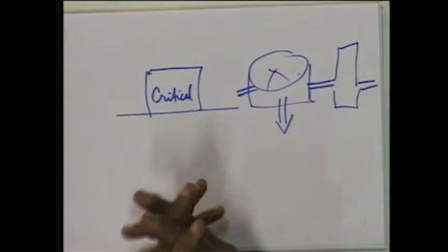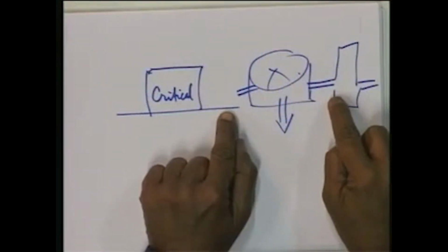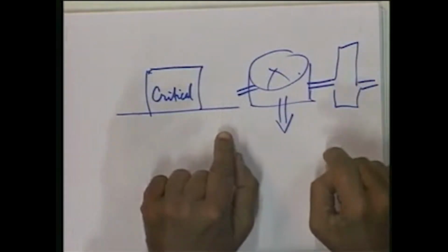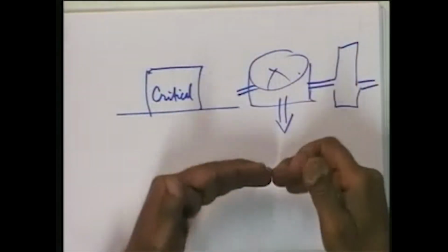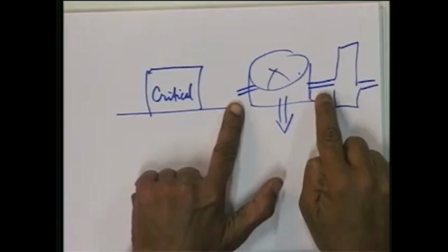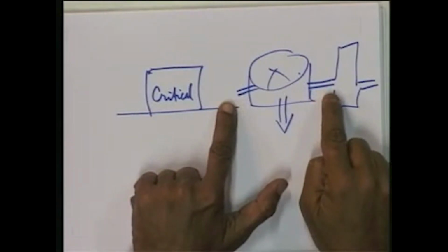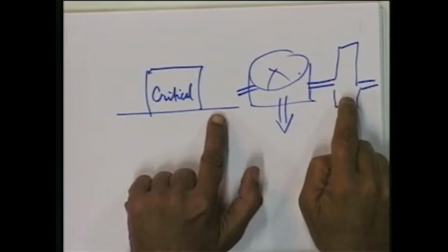It does not need much explanation to see this kind of consolidation. So, imagine the effect of this kind of consolidation on the pipes to which they are connected and their effect on the other structures. It is very easy to visualize that as this tank settles, if the settlement is exorbitant, there could be a rupturing of these pipes. If these pipes are carrying dangerous chemicals, then rupture of these pipes could lead to disasters.